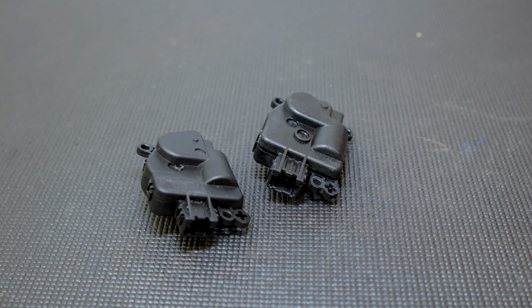We have one on the left and one on the right. But if we look at the other unit, we have a 5-pin actuator. And so even though these may look similar, there can be differences. Now I went ahead and got our tabs broken off here just so I can show you that when we look inside of these actuators, there are going to be differences depending on the wire count.